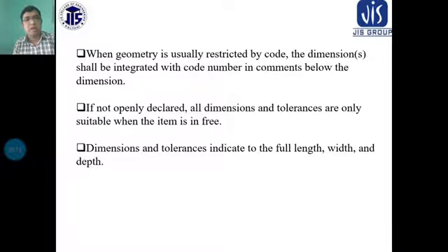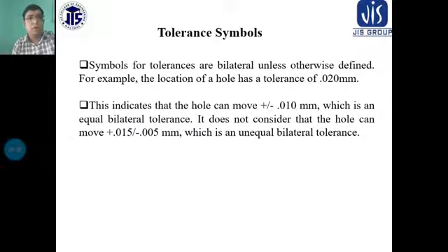That means the dimensions and tolerances apply to the full length, width and depth. And the tolerance symbols are given. The tolerances are bilateral unless otherwise defined.